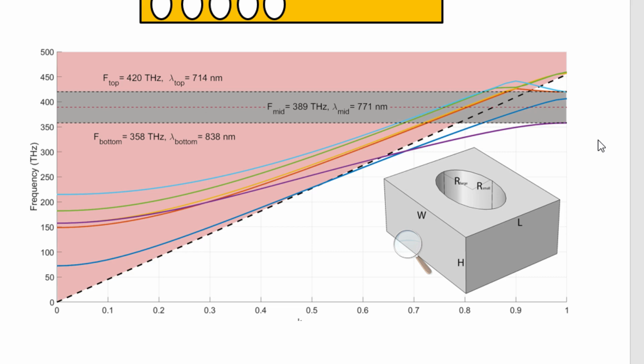a band gap, you normally need the effective index contrast. The larger the contrast is, the bigger the band gap is. The problem with photonic crystal is that the photonic contrast is between vacuum, which is the hole, a little bit of vacuum, and a little bit of silicon around it. So it may be a factor of basically 2 to 3 difference. So this is not so big of a difference to create a huge band. As you can see, the complete band gap area, which is at the top of that gray area, is very small. But fortunately, you can have quasi band gap.